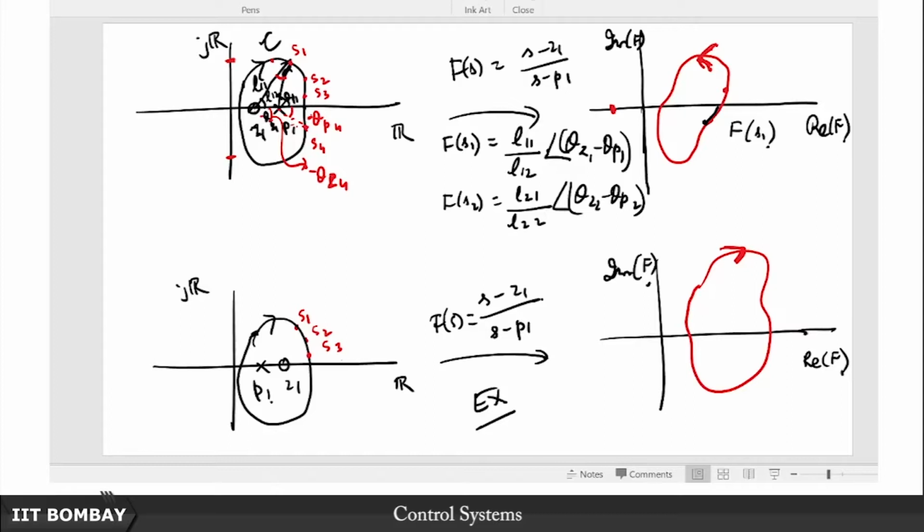Of course, depending on the relative location of the pole and the zero, the sense of the contour can be plotted, but it is not of much interest to us, because the crucial aspect that we were looking for is how many times it encircles the origin, and we saw it is 0. And we illustrated this geometrically. We showed that eventually this angle, the phase, is the principle of arguments, which is angles of complex numbers. If you have one pole and one zero, then the angle difference is given by this angle in this triangle, right.